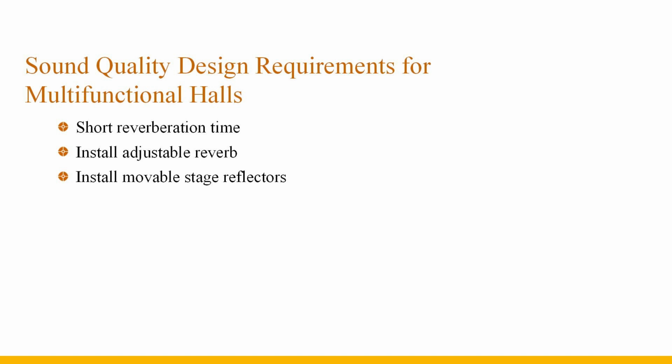The purposes of the multiple-purpose hall include meetings, movies, drama, and musical performance, etc. There are stages and auditoriums, electroacoustic systems, and most of them have orchestral pieces. Therefore, the main principle is to be suitable for electroacoustic sound reinforcement, and the reverberation time is short. By installing an adjustable reverberation device, it can be adapted to different functions. Adjustable reverberation devices include both electroacoustic and architectural designs.